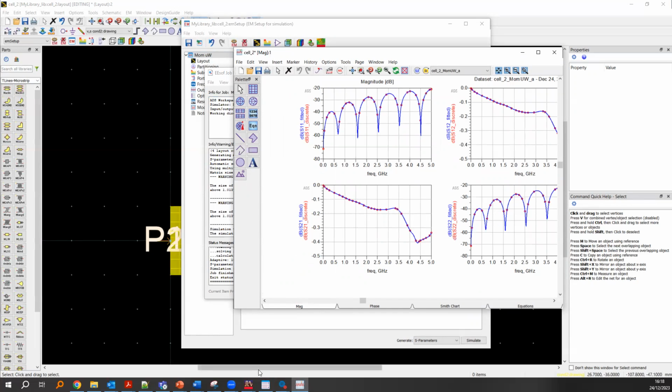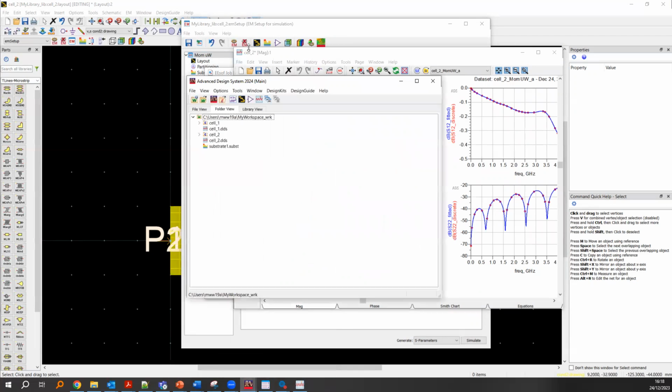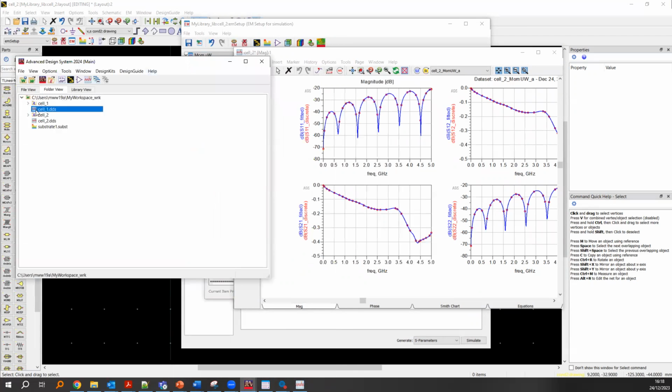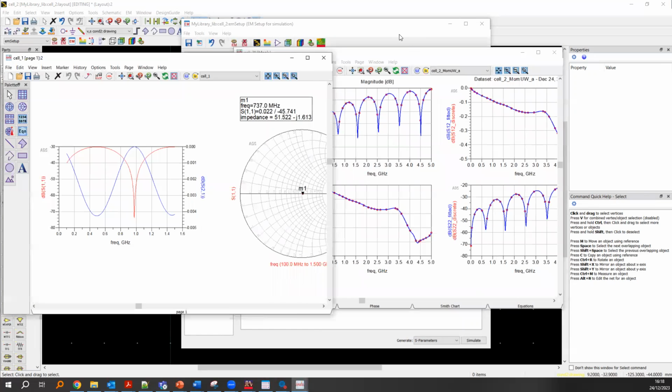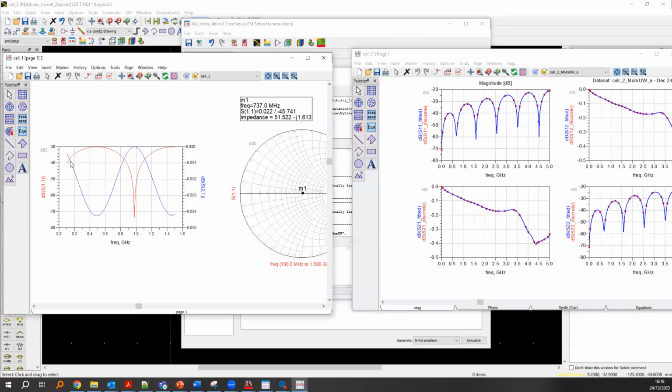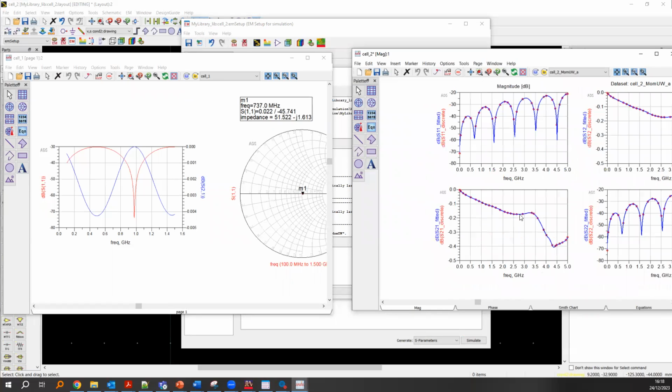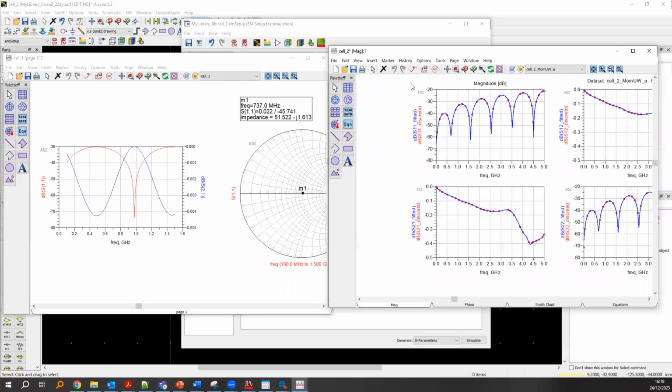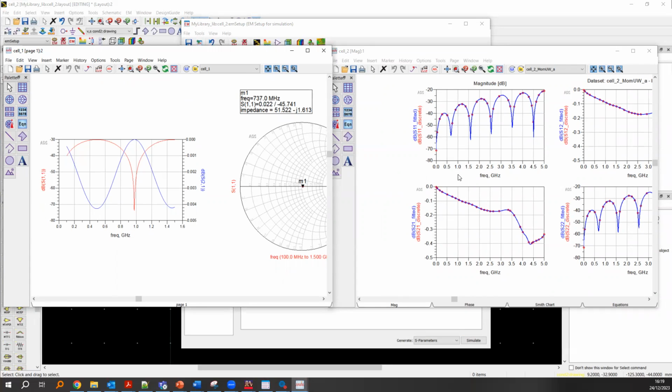If we compare that to the previous menu, which is a simulation of your schematic, you will see that there's quite a high similarity, but there are also some differences. If you look at the S21 data, previously we were getting an S21 of about -30. Now you can see that this degrades as you go higher in frequency, which is to be expected. You can also see that the signal transmission has some loss, even though previously the signal transmission did not have loss. So one of the things you'll be exploring in the lab is optimizing these parameters, and in future labs, modeling them in order to understand the loss sources, identify how to optimize these parameters, and you'll also compare these to measurements.